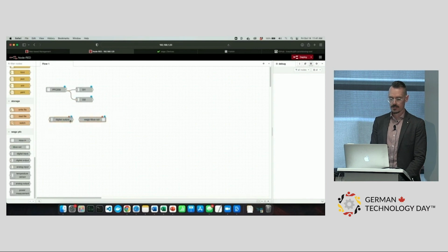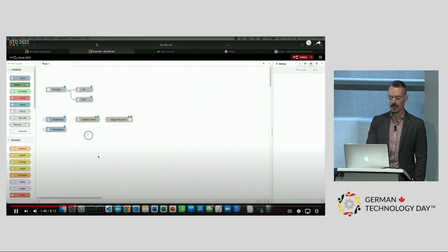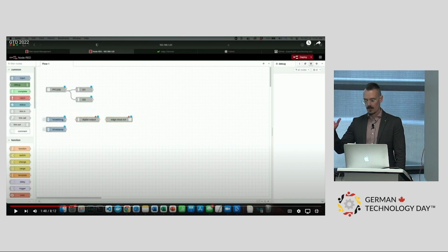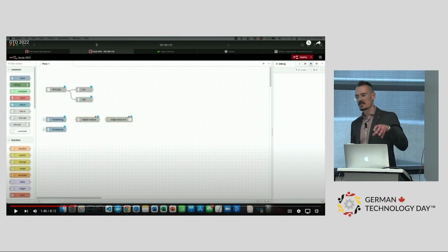So in this case, if you guys come down and see the demo, I'll show you how I have physically wired, but I basically have the inputs wired to the outputs. I needed some way to show you guys how I'm triggering the inputs, how the input is actually getting a message. So I physically have it wired, and I'm going to send data to the output saying turn the output on, and that's going to show the input turn on. So it's just physically wired in the loop here.